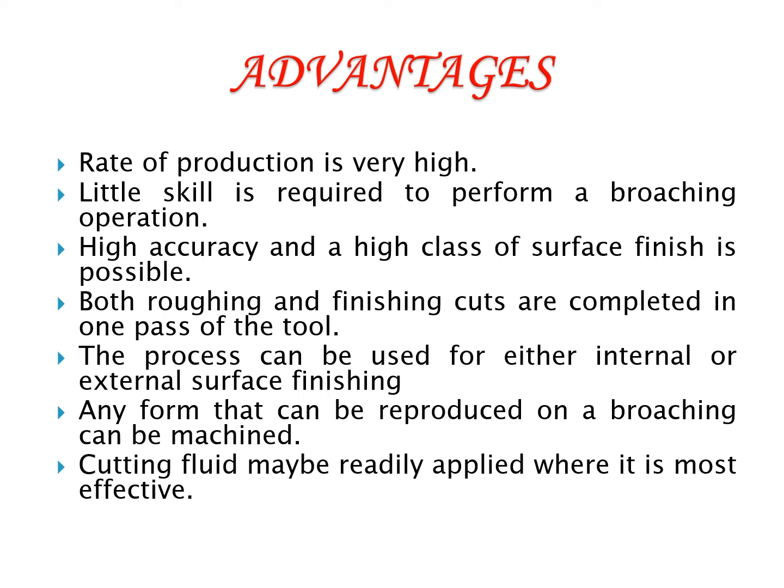The process can be used for either internal or external surface finishing. Any form that can be reproduced on a broach can be machined. Cutting fluid may be radially applied where it is most effective.